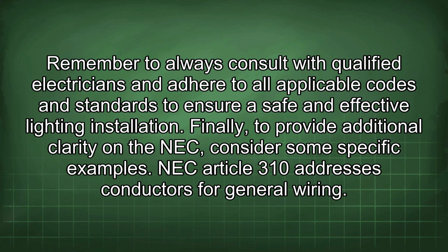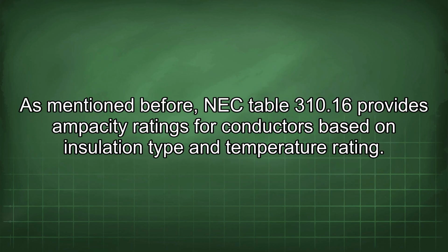Remember to always consult with qualified electricians and adhere to all applicable codes and standards to ensure a safe and effective lighting installation. Finally, to provide additional clarity on the NEC, consider some specific examples. NEC Article 310 addresses conductors for general wiring. As mentioned before, NEC Table 310.16 provides ampacity ratings for conductors based on insulation type and temperature rating.